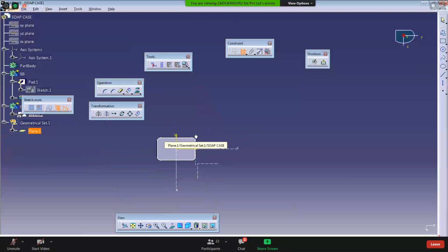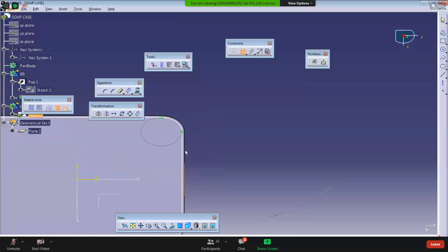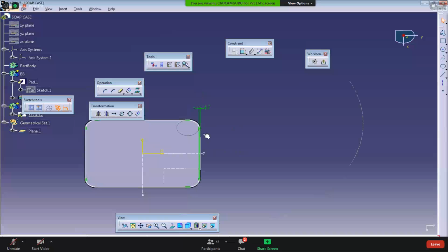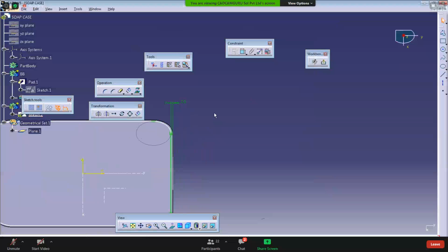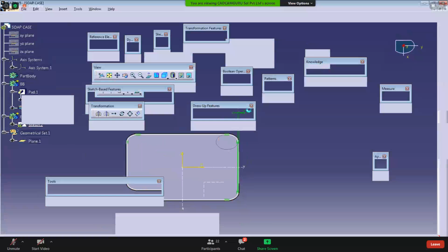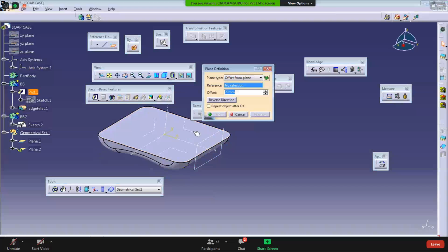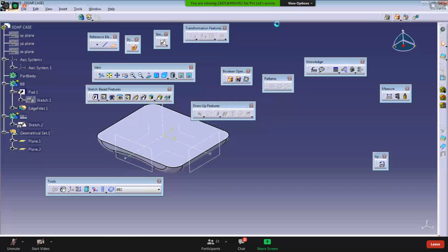So from this plane to this line, you can give the dimension. Plane reference is fine. You can check it here. It is a reference you are using, but that is a plane reference, doesn't matter. It depends on the reference plane, but not on bodies. Okay. Similarly, from other sides also, we can introduce the planes. So I exit here and apply the plane here. So that plane at the distance, how much is it? 120, right? So this becomes 60.